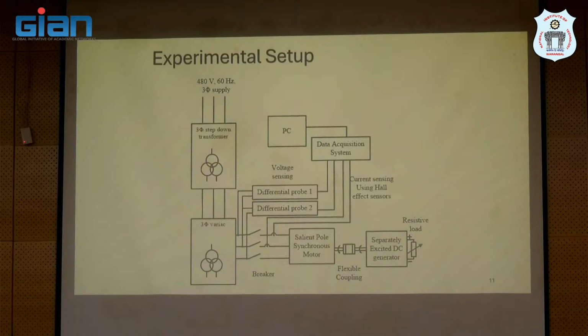And typically for a permanent magnet motor, you will need to sense the position of the rotor and create a closed loop to drive the motor. So it's a little one step more. You need to know how to do that inverter driving of a PMSM before you can get into the actual data collection process. So these are a few things.